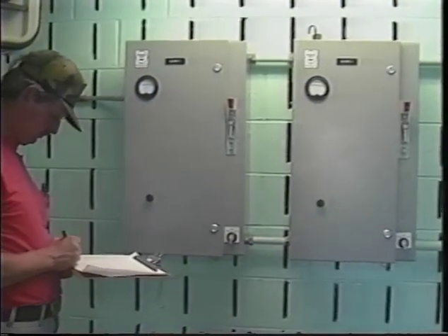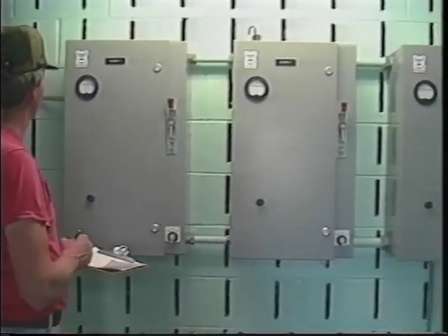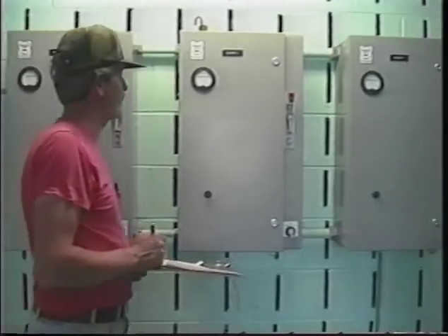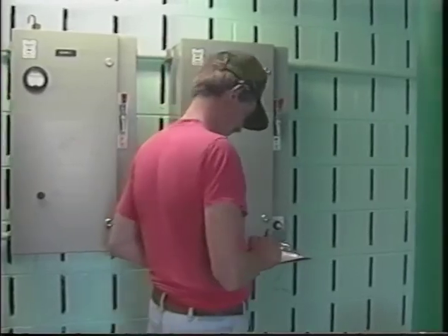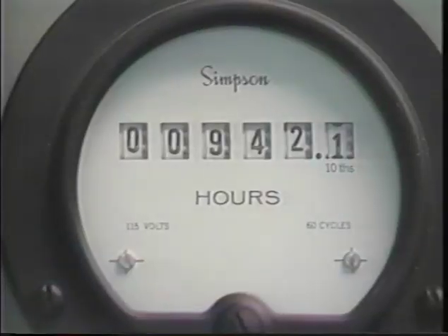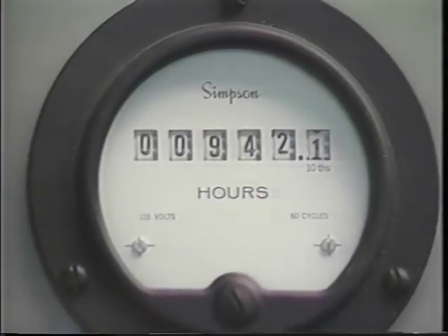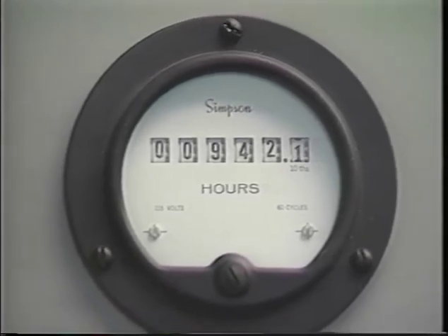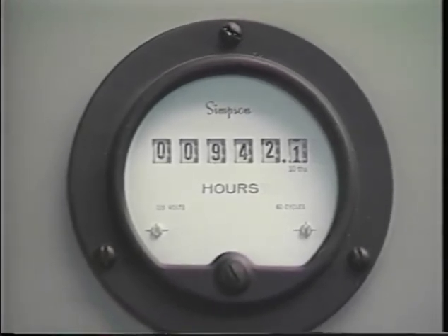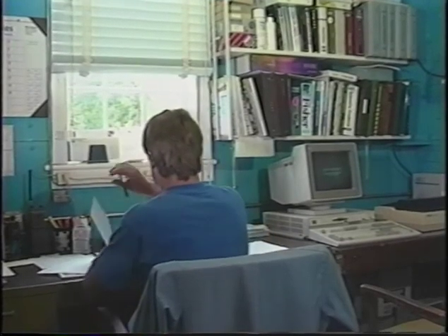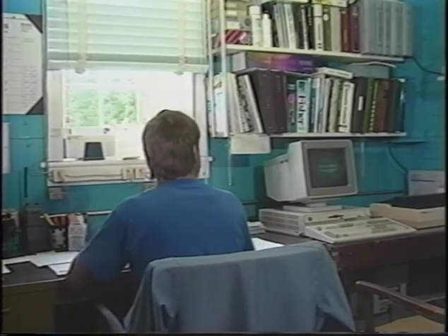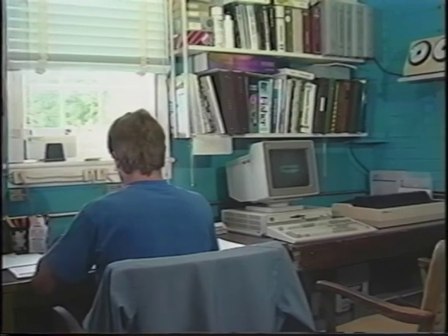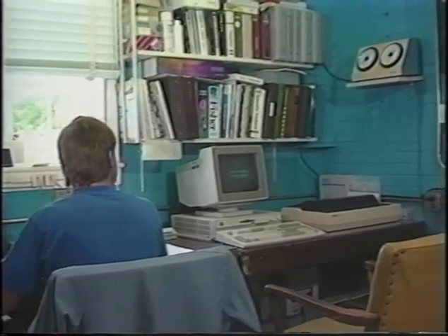Generally, lagoon systems do not require as much process control attention as a comparably rated activated sludge or trickling filter facility, but proper process control testing and decision-making by skilled treatment plant operators is still a must. The facility NPDES permit specifically requires operators to be familiar with the efficiency of each treatment unit.